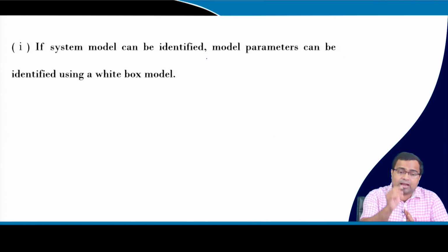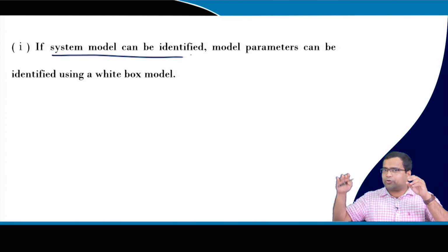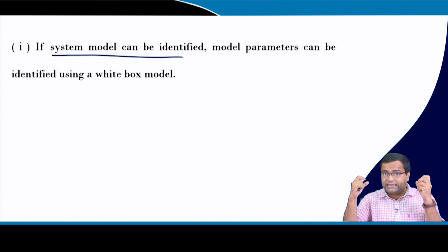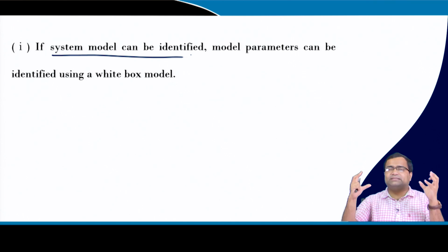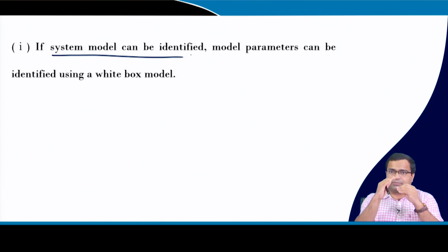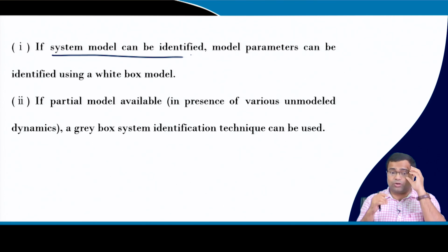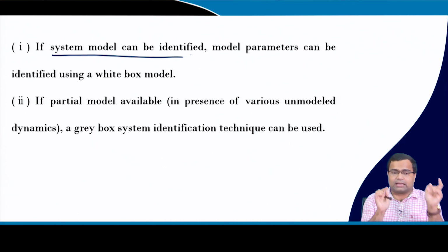Now, you did a practical test of a converter and you try to derive the model, but nothing is known inside the converter except for the inductor and capacitor. So you need to obtain the closed loop output impedance expression. We may not be able to model everything. So from the measured response, if we want to match, and we know some information about the converter, for example in the buck converter we know that on the output side there is an inductor and capacitor, then we know the circuit and can derive the model and try to match. That is the white box model.